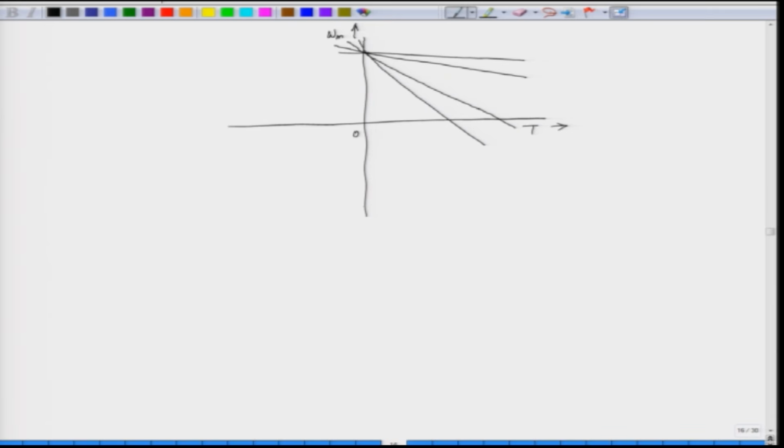Similarly, if we go for reverse motoring, we have the profile like this, and if we further increase the resistance, it changes. So this is, let us say, the no load speed in the forward direction, omega m naught, and we have the no load speed in the reverse direction, minus omega m naught.